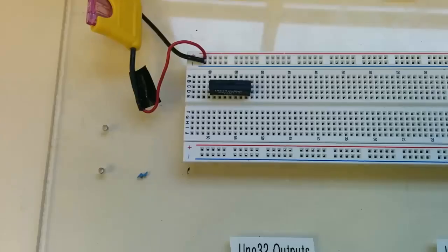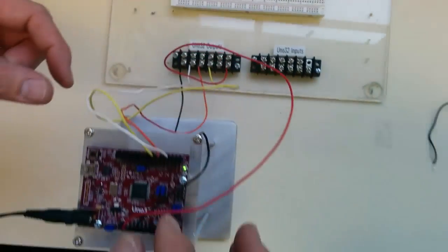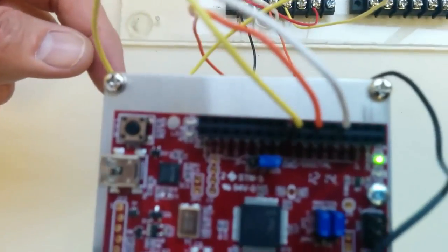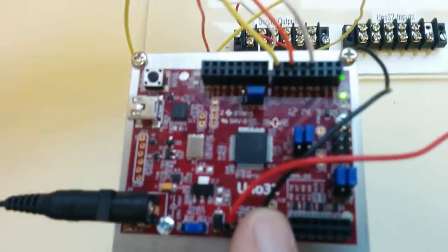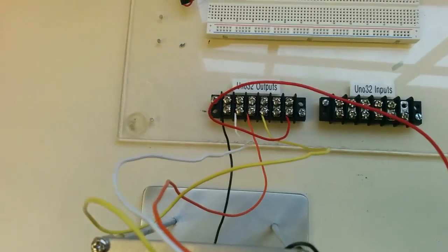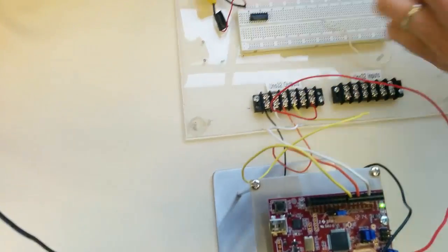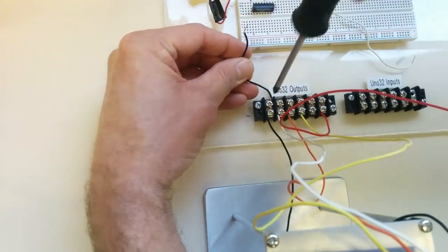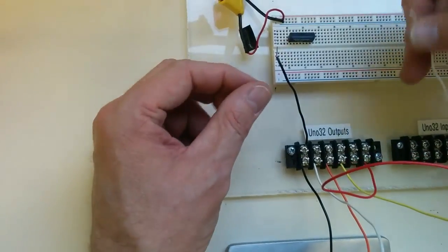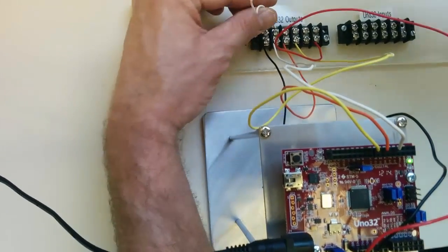To complete the first circuit, we're going to need to go from the UNO 32. So if we back up and look at the UNO 32, just like with your motors, we take digital outputs to the board. We're bringing ground out here and it brings it down to the terminal block. So we'll set ground. We'll hook ground in. Ground comes out, and we're also going to need one of the digital outputs, and we're going to use the white one and try to keep the wiring consistent so it's easy for everybody to help everyone troubleshoot.